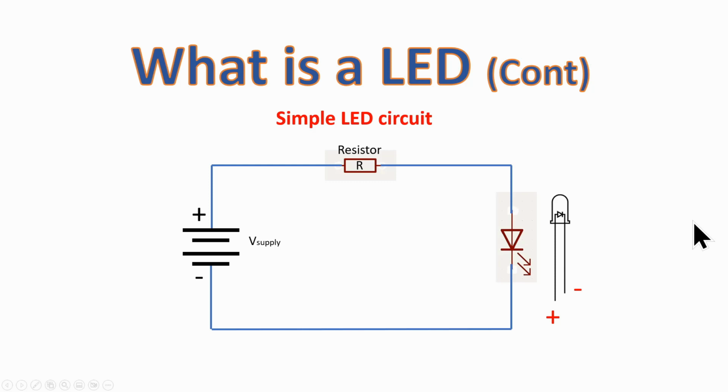So let's create a circuit. We're actually going to build this circuit and show you how it works. And then we're going to play around with resistance and see what that does to the light. Well, the first thing we have to do is determine what the resistance should be. What do we know? We're going to know what the supply voltage is. In our experiment, we're going to use 3 AA batteries, so that would be 4.5 volts. We also have an LED.